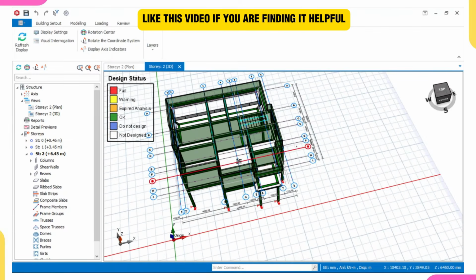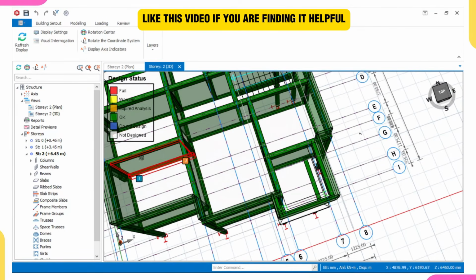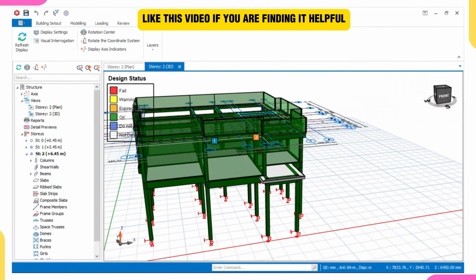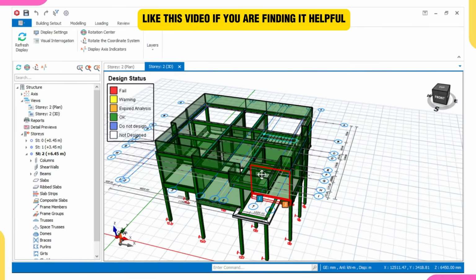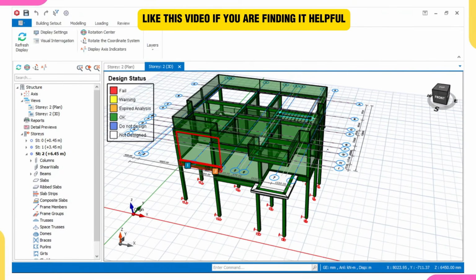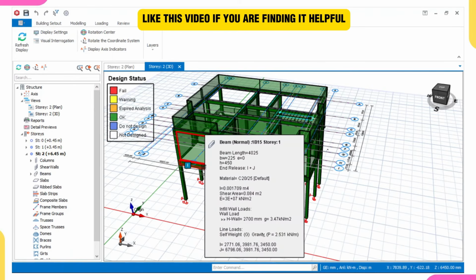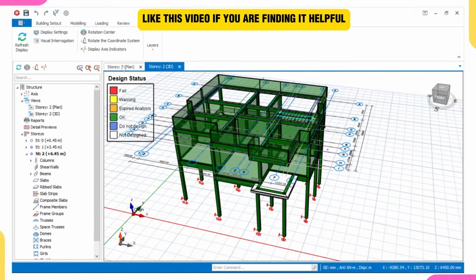For example, look at our slabs. Our slabs, they are all on white. The reason is because we have not yet designed our slab. But these are the things we'll do in this video. And if you get your drawing after design and you're seeing it like this, all of them green, don't just leave it like that and go. Do interactive design. So let's come to our story plan.